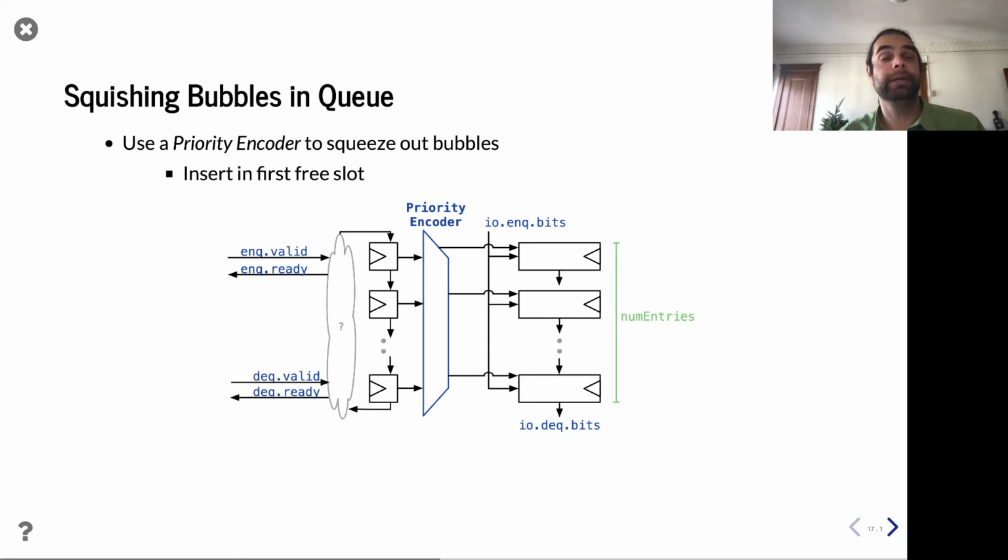When you go from 1 to 0 you're tossing away energy, but going from 0 to 1 you need energy to charge it up. As a designer, the best way to save power is having less hardware, and the next best way is to reduce your activity factor. With the shift register, by copying data down when we shift, we're writing all n registers, so potentially a lot of bits toggling. That might not be good for power.